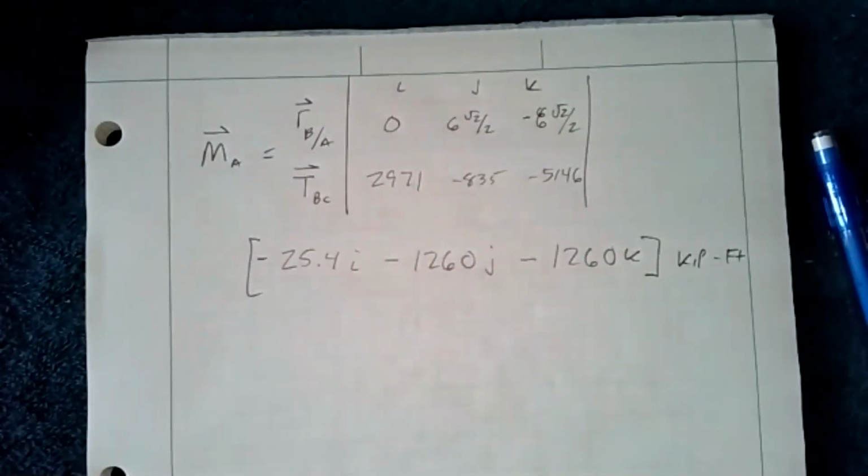All right. So that's those two examples. I hope they make sense. This should help you with the homework. As far as moments about a point, that's it. Whenever you take a moment about a point, you just find the respective vectors and do your cross product, and you're done. That's all. Now I know that's not super exciting at this point, but again, we're building the structure that we need to go on and solve more interesting problems. So bear with me; it'll become more relevant as we work ahead.